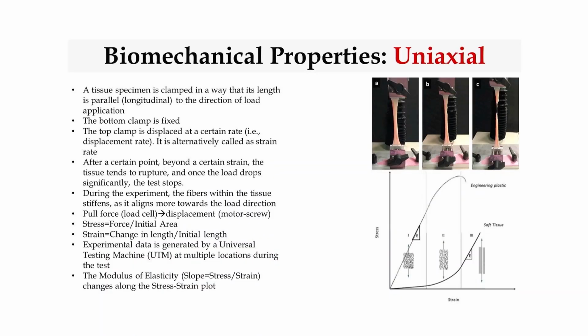Another thing to note here is, while we are talking about the modulus of elasticity, what I had just indicated, this is not like hard materials or metals. The slope keeps on changing. So can you define a single modulus of elasticity for this entire model, the stress versus strain or the model response? You cannot. So there is a range of modulus of elasticity which you want to describe or report. Let's say the modulus of elasticity goes from 20 megapascal to 75 megapascal. This is how you have to define it.